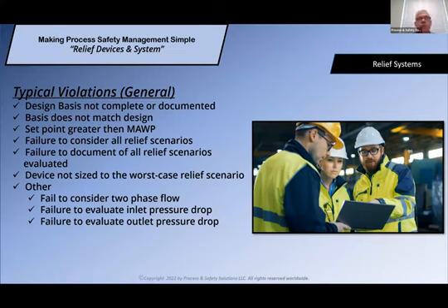Failure to consider all relief scenarios. Remember, I said when we first started this discussion that you must document and evaluate all relief scenarios that are potentially there. 24 of them for that matter. Most of them you can go through fairly quickly and say they don't apply. But typically 2 to 3 of them apply in almost every situation. Fire case, blocked in case, loss of cooling case, et cetera. There are numbers that apply in just about all situations that you must look at and evaluate. So you may have 3 scenarios that apply. You must document what the relieving scenarios are for each of those.